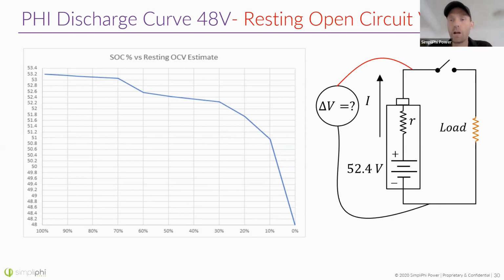What temperature do you recommend for better health and long life of these batteries? These batteries operate very well in temperatures from 25 to 40 degrees Celsius. It's really the humidity in the air and other factors that influence the life. If you're in a low temperature environment, consider reducing your charging rate. The charging rate can influence the lifetime of the battery, because the lithium can start lithium plating on the charge cycle, because the lithium can't get into the graphite layer, and so it slows down.